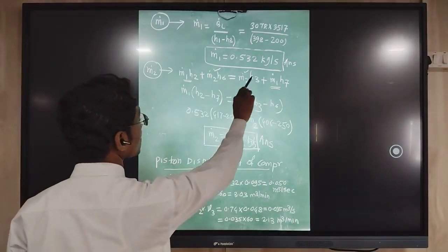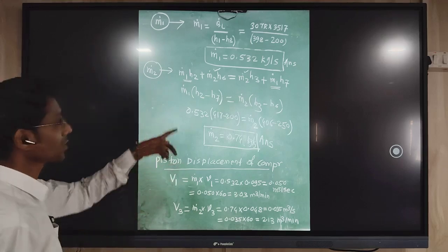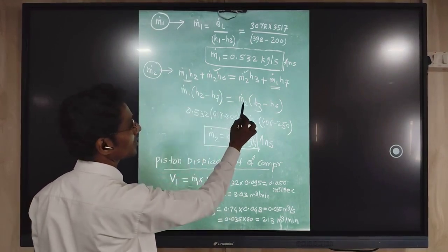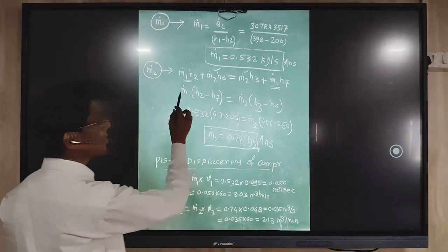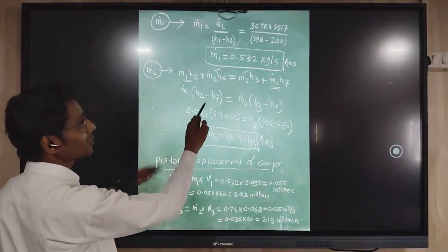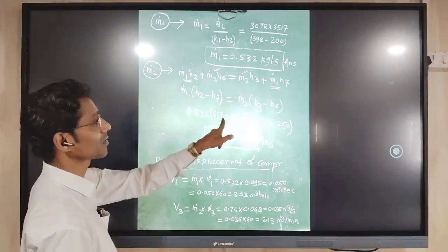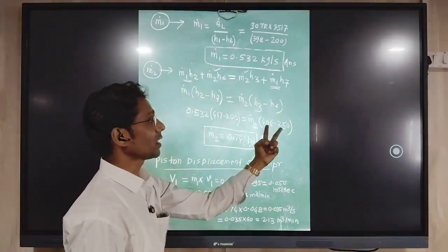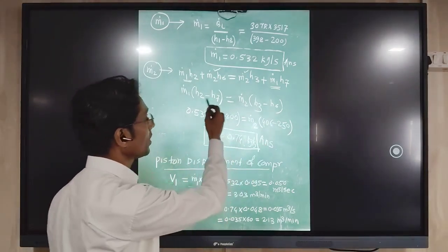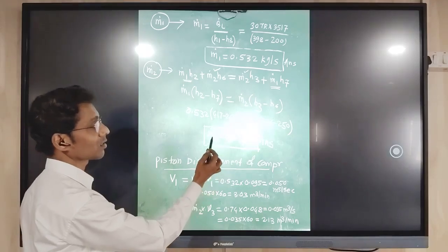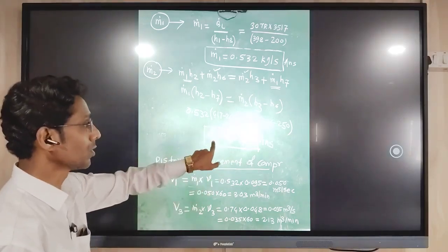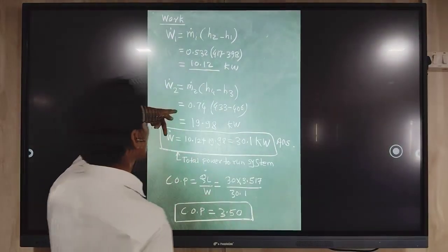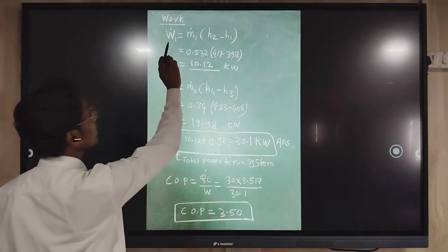First of all, we arrange this formula for easier calculation. We take the m1 dot mass flow rate terms on one side and the m2 dot terms on the other side. In the brackets, we put the corresponding enthalpies enlisted in the last slide, H2, H7, and the calculated value of m1 dot. m2 dot is unknown, and H3, H6 enthalpies from the previous data we put here. By doing this calculation, we find the mass flow rate of high pressure compressor 2, m2 dot.